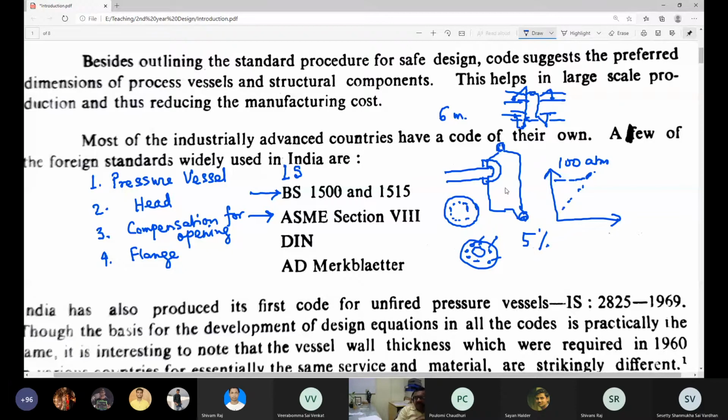So the soft material will try to adapt to the surface roughness, and so that creates the sealing effect. Okay, so there are a lot of other considerations. When we tighten the bolt, what kind of stresses are we subjecting the gasket to, and how many bolts do you need? Those kind of details we'll work out in this number 4.